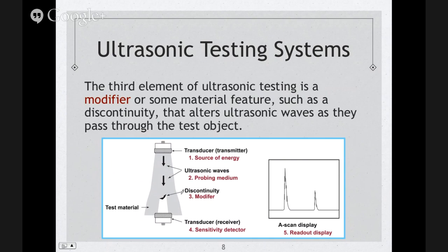In the case of a pulse echo technique, we know that the impedance ratio is going to be the impedance ratio between our defect and the materials around it, being this material and the air inside the crack, if it's a crack. That would give us the reflection ratio or percent that would reflect back into our transducer. Our impedance ratio would always tell us how much transmission you have and how much reflection you're going to have off that interface. So we're going to have an interface in a pulse echo technique.